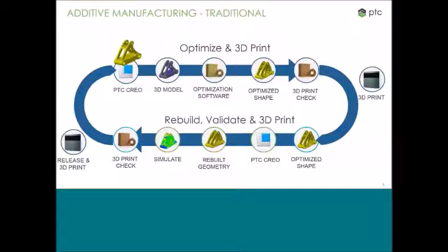And then they take a look at it and say, hey, was this a worthwhile print? Do we have thin walls here? Did this break under construction? Is this going to hold the structural integrity that we need to? And then once they analyze this physical product, they then go back into it and re-optimize the shape, they go back into the CAD, they rebuild the geometry, and this could be an endless process until they get the design that they need.